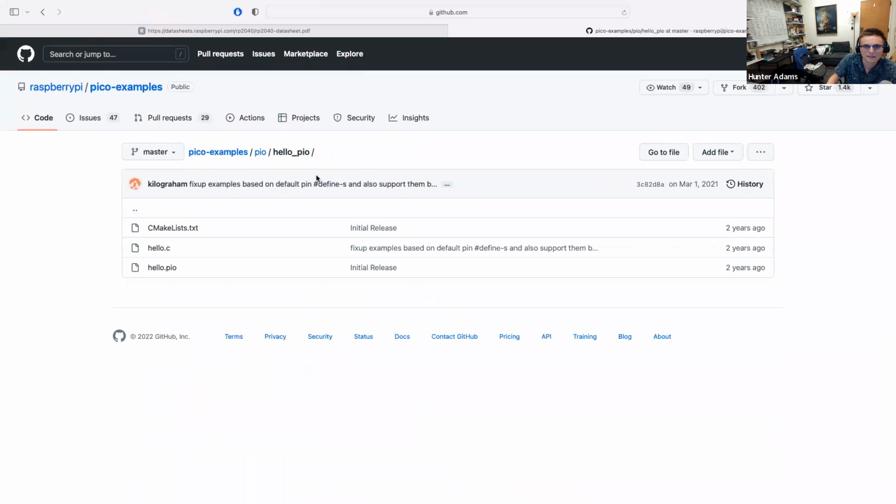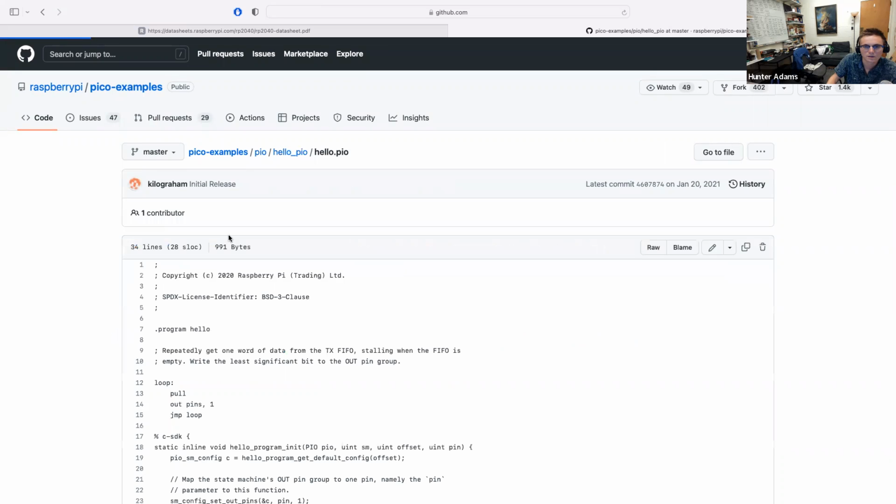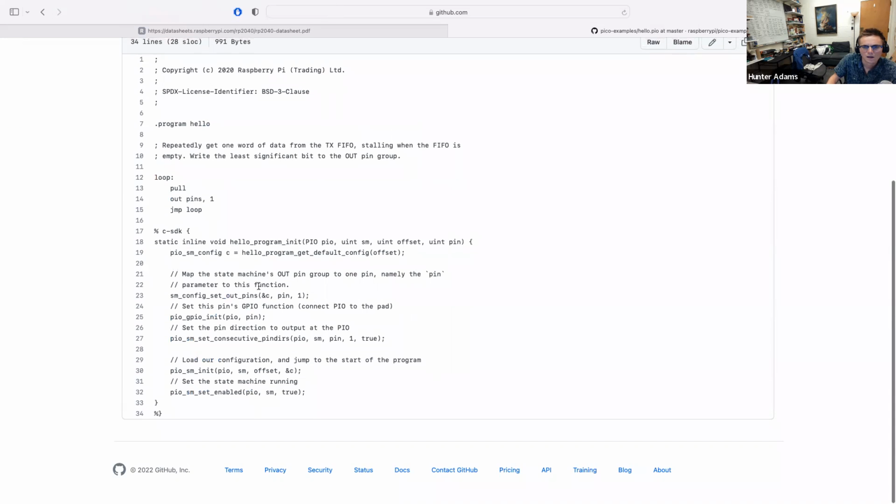Okay, what else is happening in that initialization? We then call a PIO GPIO init on that pin number, which again, we could take a look at, but this is associating that particular GPIO pin with the PIO as being driven by the PIO coprocessor, in much the same way that we could associate a GPIO pin with, say, an SPI peripheral or with an I2C peripheral. In this case, we are associating that GPIO pin with the PIO.